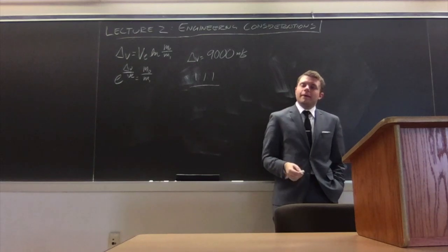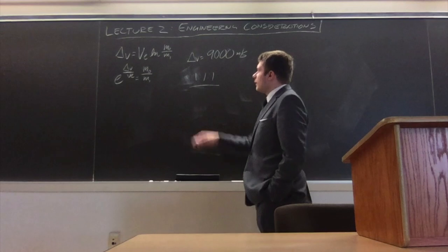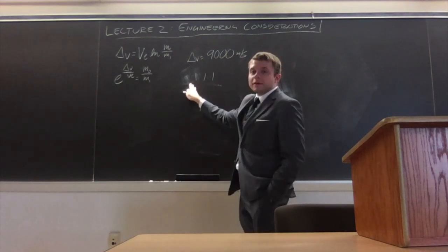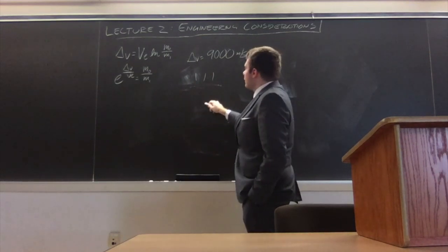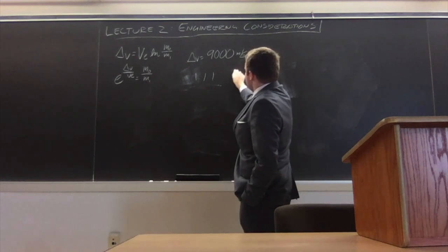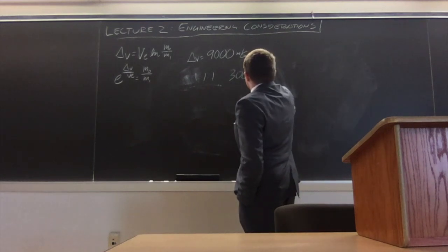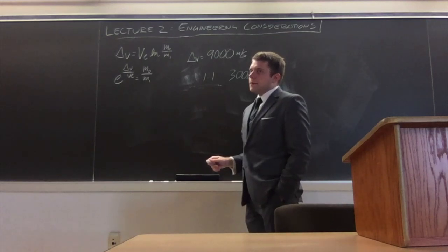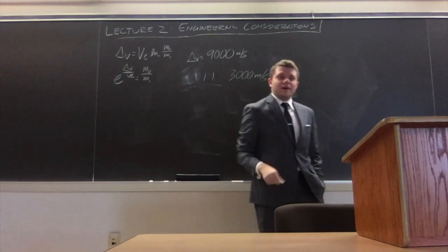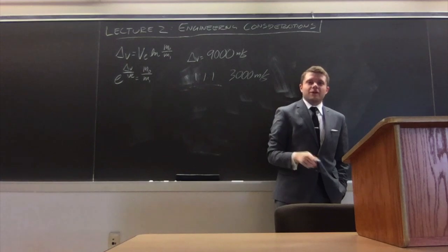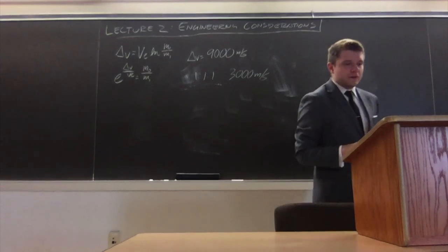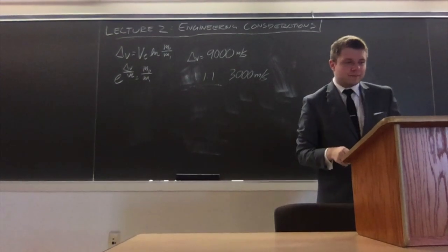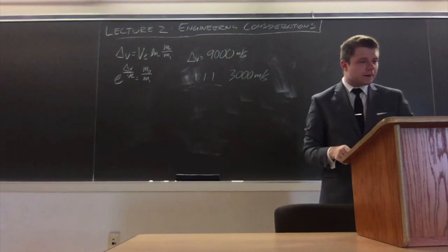Yes. So when you say 1-to-1-to-1, this is 1-to-1-to-1 for the delta V in the stages. So for a 3-stage rocket, that means that each stage has a delta V of 3,000 meters per second. Okay. And that doesn't necessarily imply that they would be the same size, right? Correct. Very good point. They don't have to be the same size. They actually vary in size. And when I talk about the derivations here, I will show that very nicely, I think.